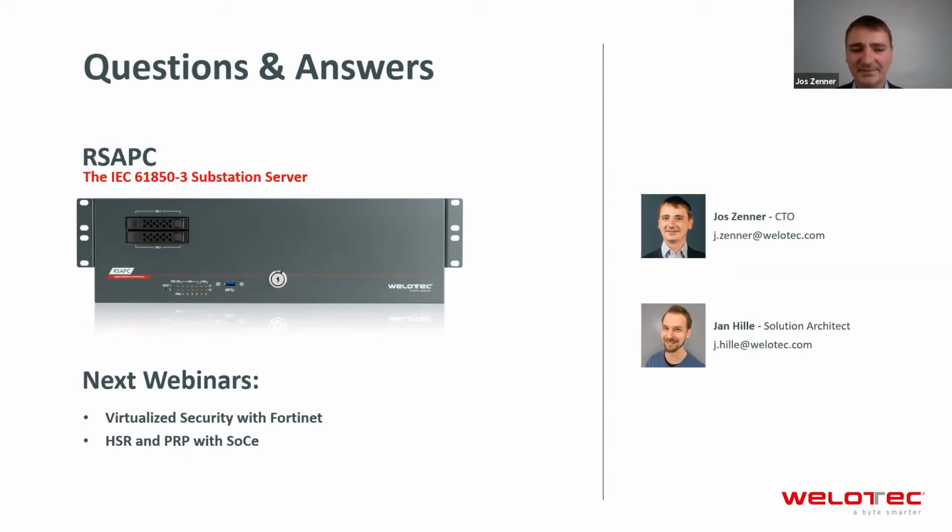It's just taking standard computer hardware, which is using a real-time hypervisor and adding the IEDs there. So you can virtualize the functionality of the IEDs and have some kind of software-defined protection and control. This means that you don't need the physical IEDs with their functionality anymore, but can just run them as software.